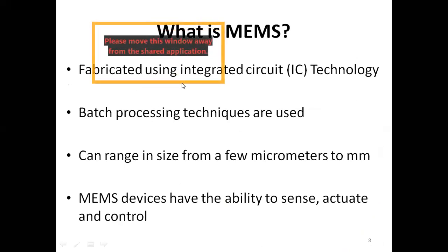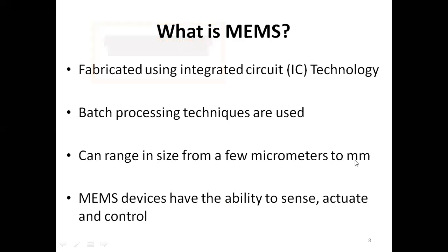MEMS are fabricated using integrated circuit, that is IC technology. Batch processing techniques are used, meaning that MEMS are mass producible, batch producible. Otherwise, they would be very, very expensive. And the size can range from a few micrometers to millimeters.